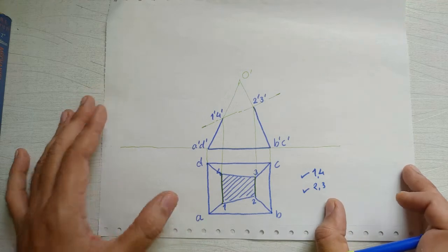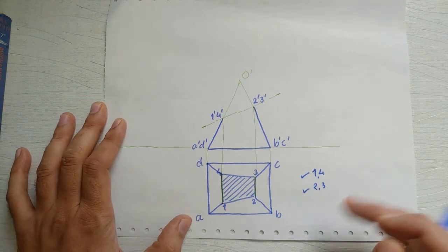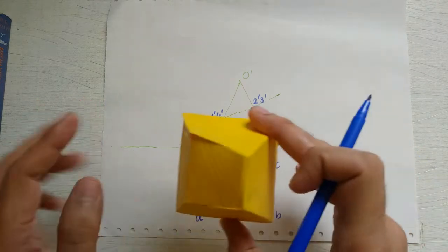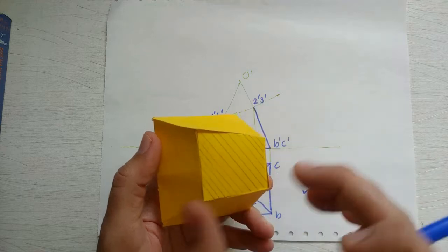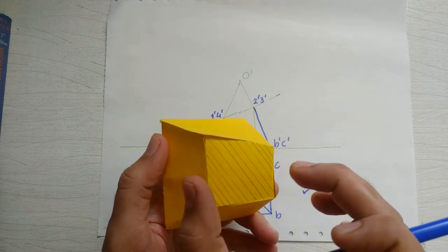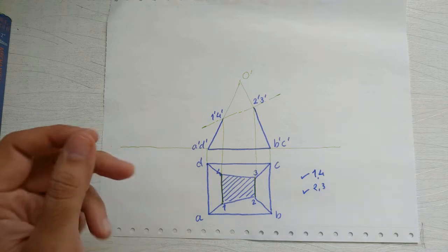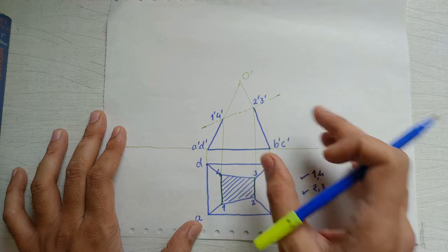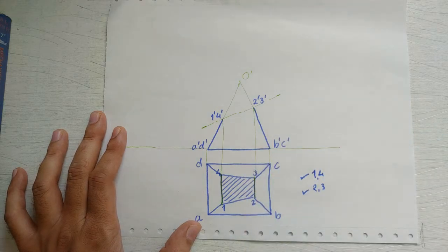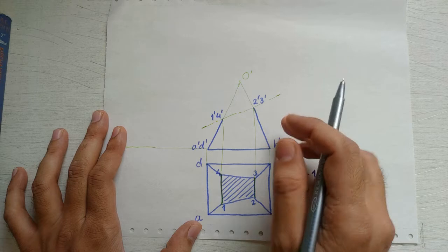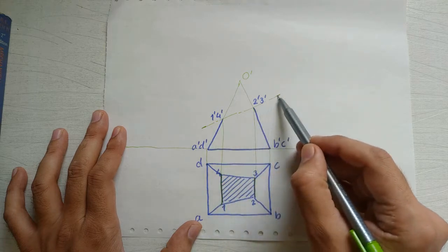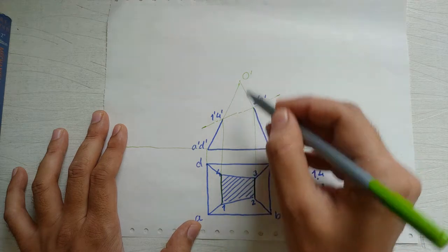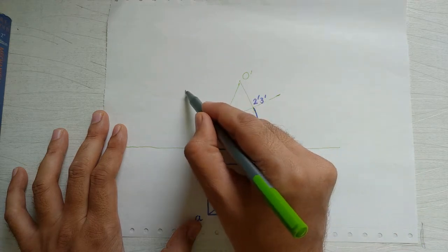Okay. Now, if we observe this section from perpendicular direction, as this is getting increased, right? So here, while drawing, it is not possible that we will tilt this and then we will see. So rather than that, what we'll do is, we will just draw a parallel line to this cutting plane line outside this drawing. So I will draw a parallel line to this.